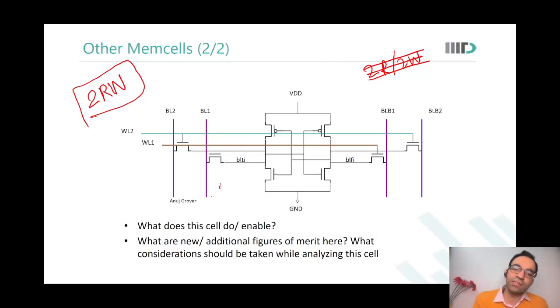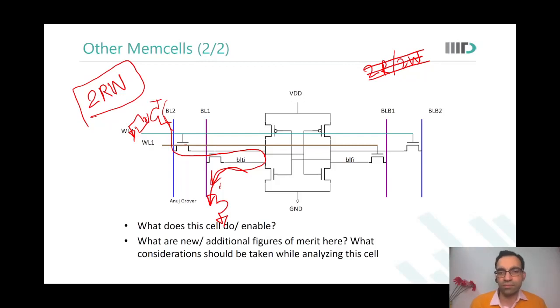Worst case for the write was that, see, there is a write driver over here. It was designed to sink this current only. But my other port also is on and the precharge of the bit line is on. So there is a VDD that is being supplied to this bit line, which goes through the first pass gate and now needs to be discharged through the write driver.